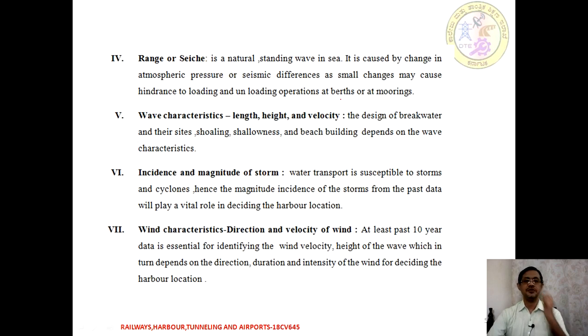Next one is going to be the seiche. It is a natural or standing wave in the sea. It is caused by changes in atmospheric pressure or due to seismic differences. Even a small change may hinder loading or unloading operations at a berth or at mooring. Hence, the seiche has to be considered according to the site condition.